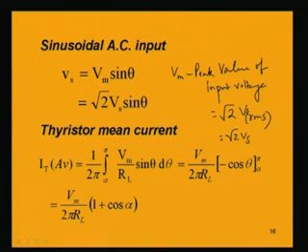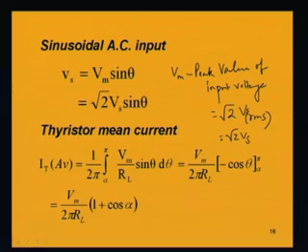So, you can find out either the current in thyristor T1 or the current in thyristor T2, but you will have to integrate properly, that is within the proper limits. For the thyristor T1 we will have to take the limits between alpha to pi, and for the thyristor T2 we will have to take the limit between pi plus alpha to 2 pi. Now, doing this integration, what we will be getting is Vm by 2 pi RL, this is the constant part taken outside the integral, and integration of sin theta d theta is equal to minus cos theta, and putting the limits of alpha to pi, so we get this expression.